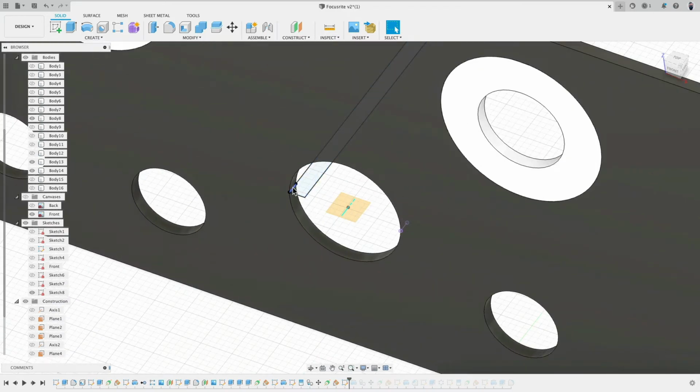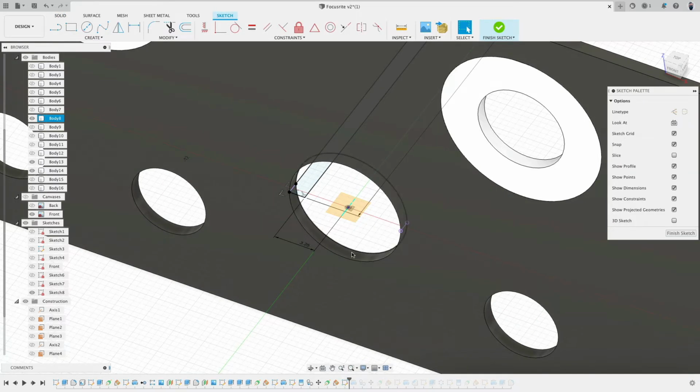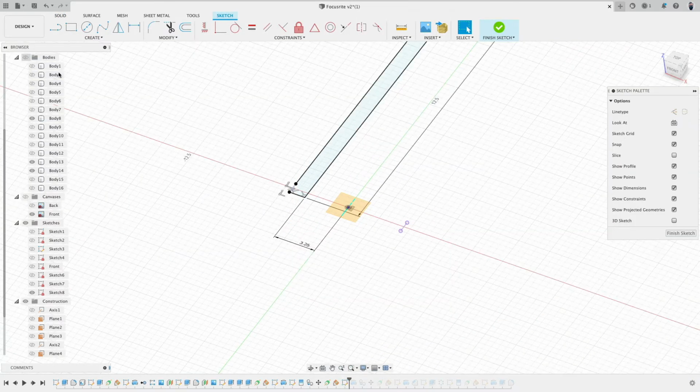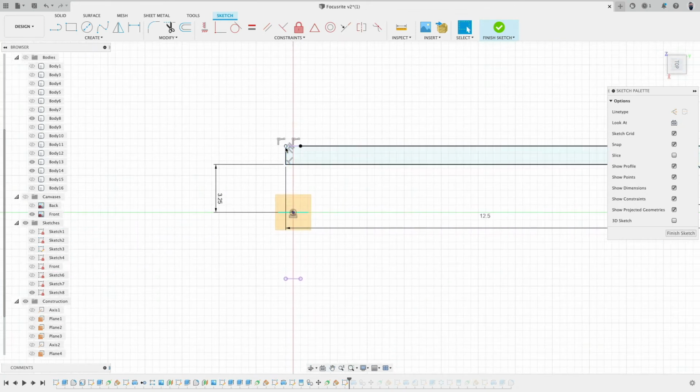So here's a small element which I found we are intersecting with that surface. And here are the dimensions. So this is flush with the front, 3.25 millimeter, which will give this then a material thickness of 1.25.